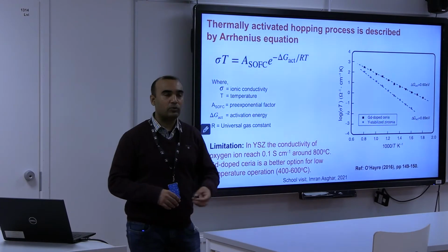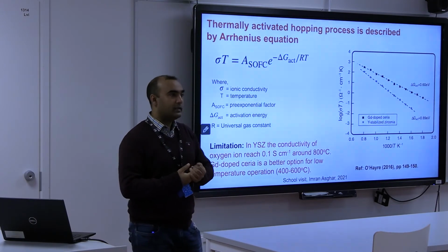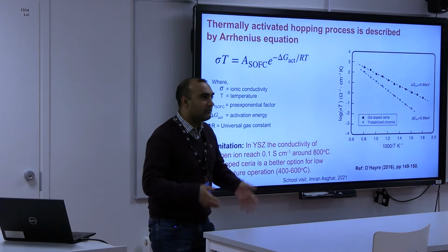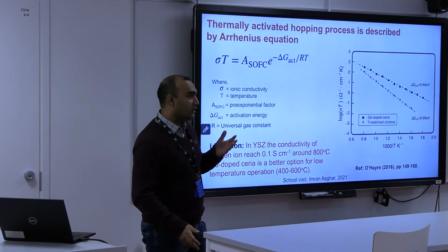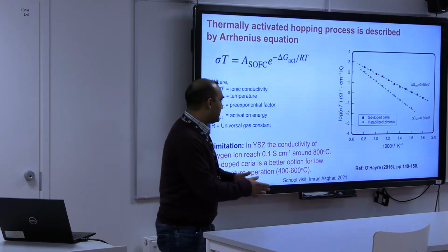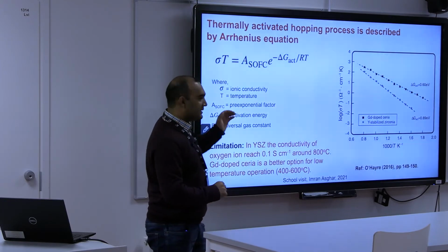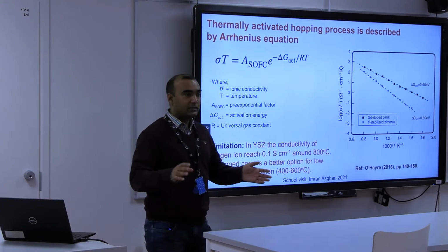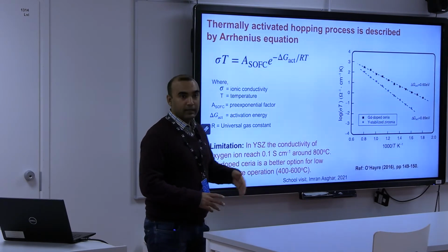So it tells about the quality of material, that if the activation energy is lower, it means that you need less energy to activate this process. But if the activation energy is very high, it means that in order to activate those ionic transport, you need a larger amount of energy so that this process happens. So the key message is that basically this ionic transport process is temperature dependent. When we increase temperature, ionic transport gets better.